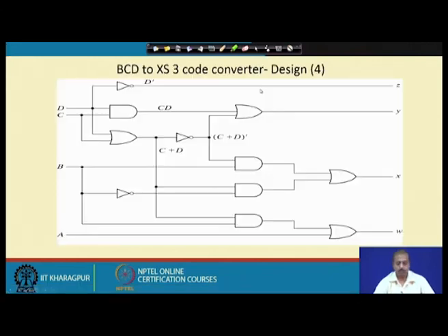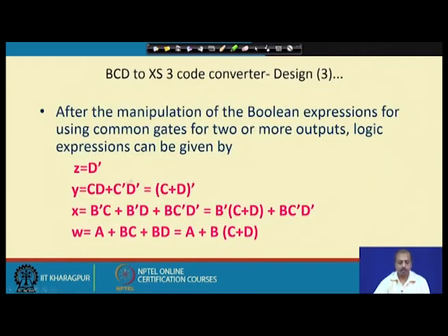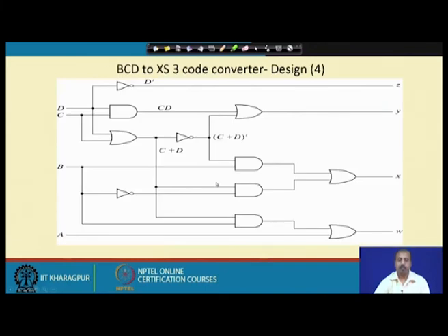This is the function for X, Y, Z and W. In fact, in this case the XNOR gate and NOR gate become similar, so for Y, instead of XNOR we can use NOR also. That will also give us a similar result because of the presence of don't cares.